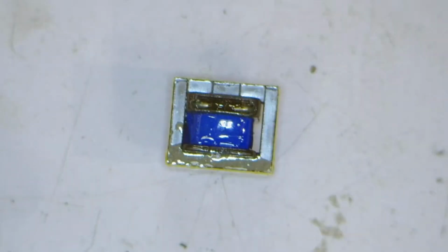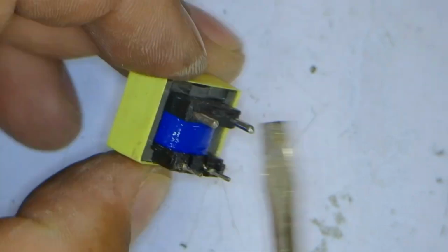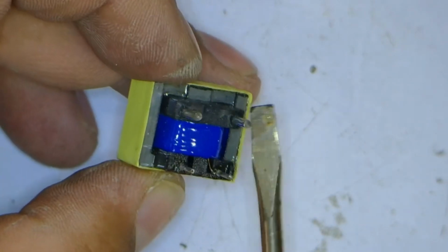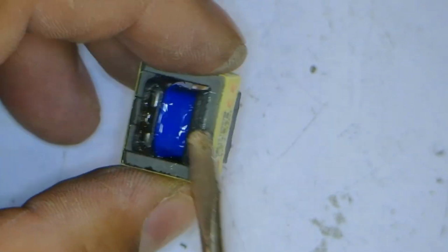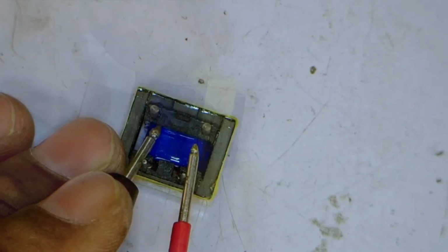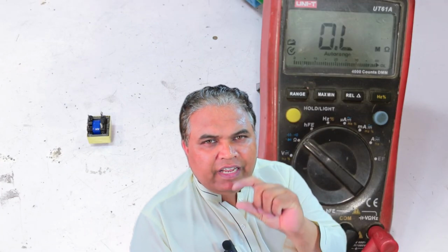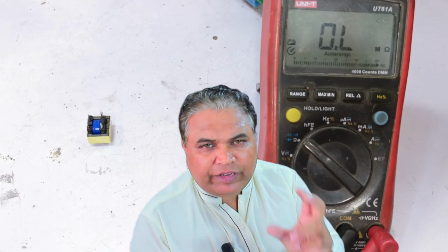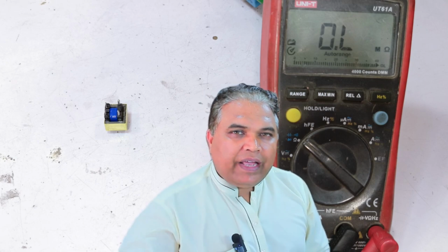I have a new current transformer. The thick wire on top is the main wire, and the 2 points here are in series with each other. The smaller wires here are connected to the coils. I will show you what the proper value of this coil should be. Now you can see that the value here is 266 ohms. The original current transformer used in the system fluctuates between 500 to 700 ohms. When the coil resistance value reaches kilo ohms, it cannot effectively transform the required low voltages, making it faulty.